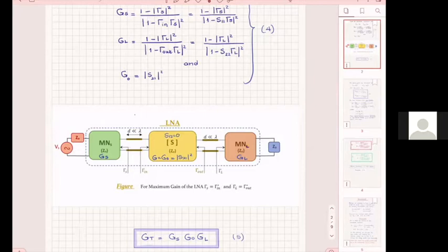However, if you try to represent your L with a section of line, in addition to omega and the change of the frequency you have there, you will also have a change in the length of the line in a way that is going to add additional changes in your circuit. And that's why you need to keep in mind that the lumped element designs are always the best. Unfortunately, they are very hard to do.